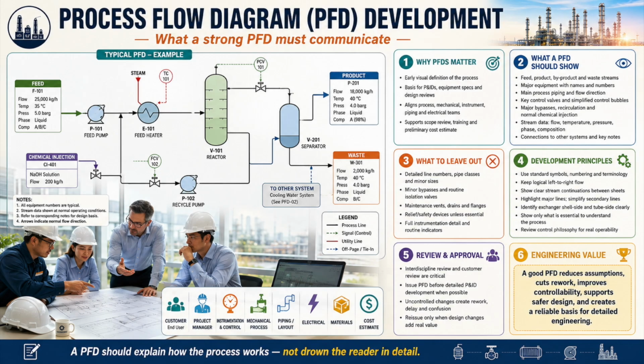Numbering between the shells of a multi-shell exchanger is normally unnecessary unless material is added, removed, or changed between shells. Brownfield modifications require particular care. New stream numbers may be needed when existing flows are split, combined, or redirected. A seemingly small modification can change the mass balance across multiple units.